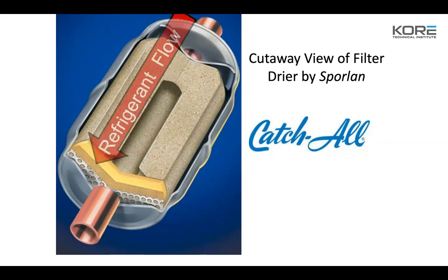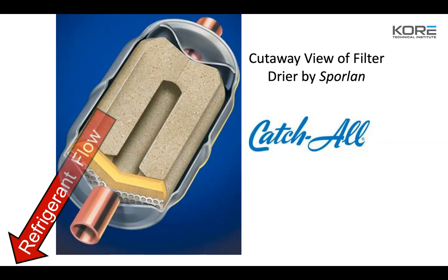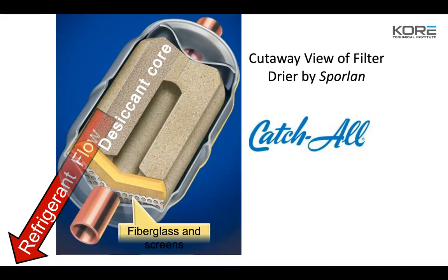So the refrigerant flow always goes a specific way. The arrows will be on the outside of that canister to tell you which way the refrigerant will flow. You've got the desiccant core inside of there, and the fiberglass screen that picks up the bigger particles.